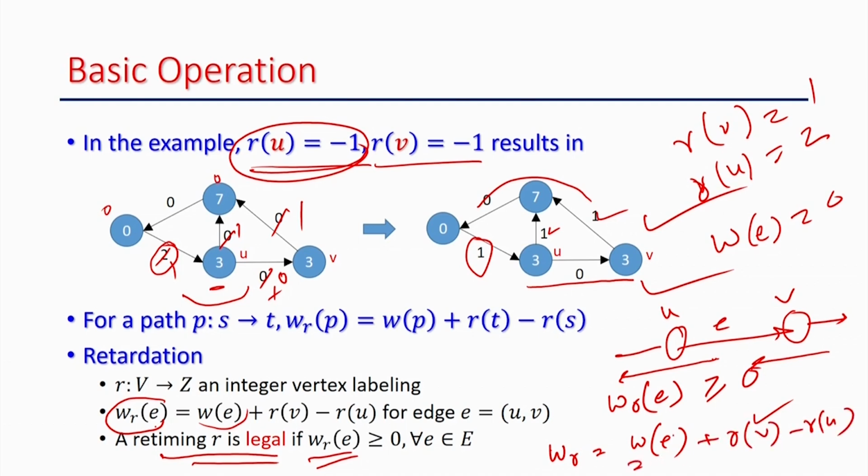So, now W is 0, I consider it as 0, this is 1 and this is minus 2, this becomes minus 1. That means you are assuming that after retiming this edge has minus 1 registers, which is not feasible. So, if you solve the inequalities and get this, it is wrong, right. So, this is not a valid solution. So, we should have some constraint on these variables, because any value is not a solution, right, because some of the solutions are illegal for a digital circuit.